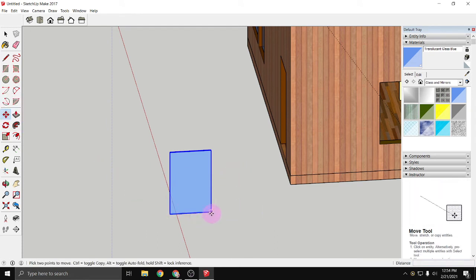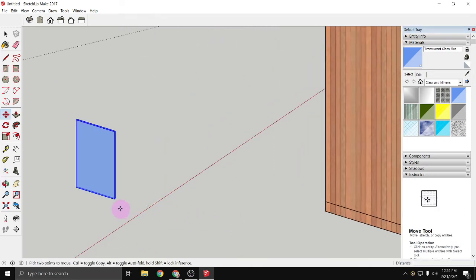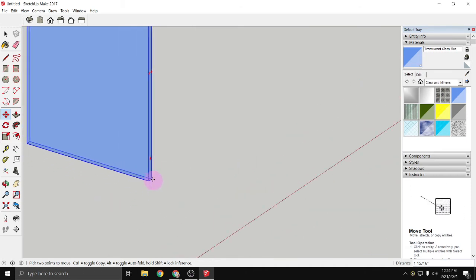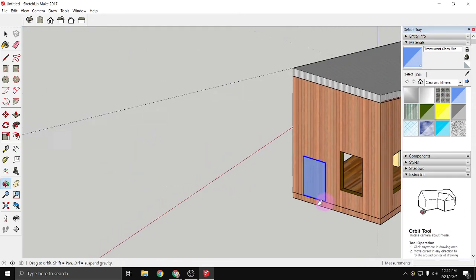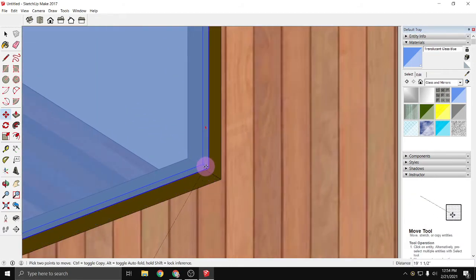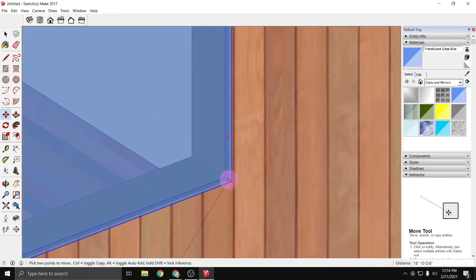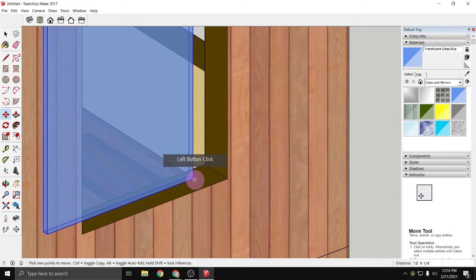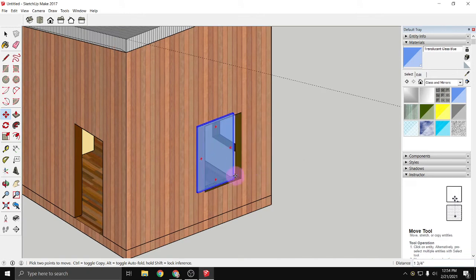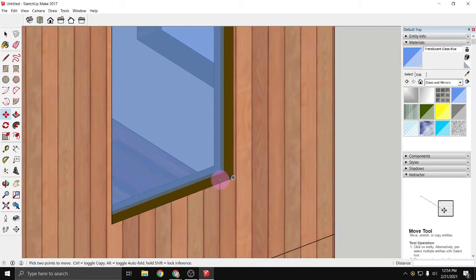And then I'll just go into the move tool. I'll grab it by itself, and if you want to have them perfectly centered, you can zoom in and grab it by its midpoint. Then I'm going to orbit around and place it. Why won't it let me place on that midpoint? Curious. Interesting. Okay, there it gave me that endpoint. There we go. I don't know why those snaps weren't popping up for a second.